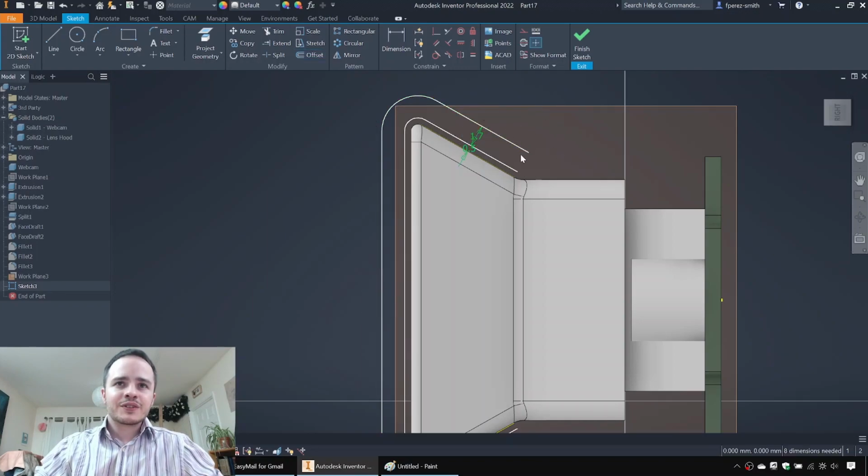Now, I'll show you a trick. We don't want to go all the way down here to make a closed off point. What we want to do is make it so that the cover only comes down halfway along here. Now, it could be a bit tricky and might screw up some of our constraints if we go the long route, so let's go the short route. We'll say line, find the midpoint of the flare here, and we're just going to draw it at a random